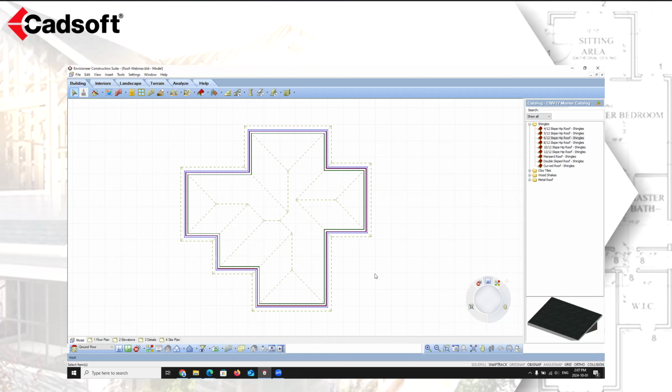The red and green arrows are surface markers. The green arrow indicates that the currently selected surface is what you're working on. Changes to most properties, such as the roof type, slope, and overhang distance, affect only the currently selected surface, which is again marked by the green arrow. You can make additional surfaces current by simply clicking on the red arrows to change them to be green.